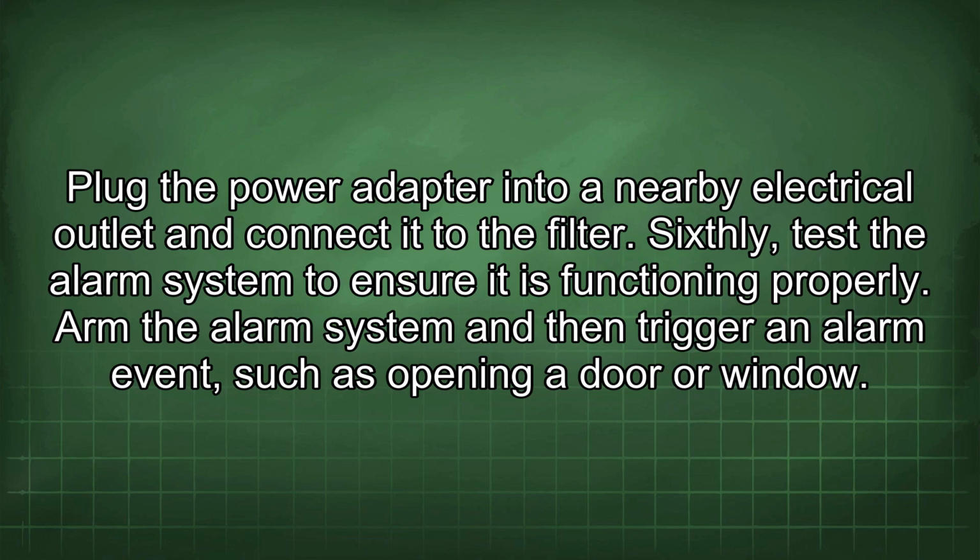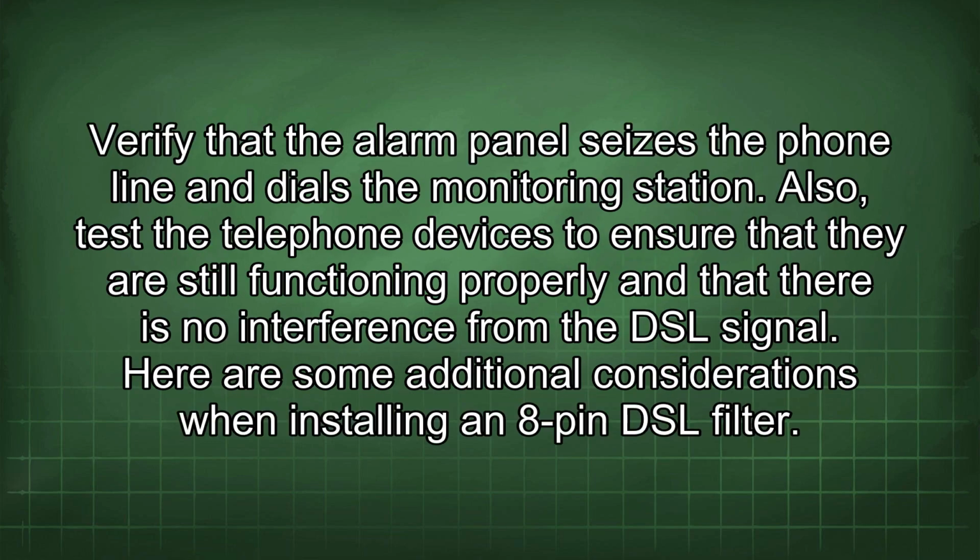Sixthly, test the alarm system to ensure it is functioning properly. Arm the alarm system and then trigger an alarm event, such as opening a door or window. Verify that the alarm panel seizes the phone line and dials the monitoring station.